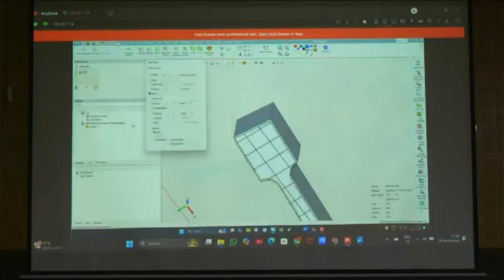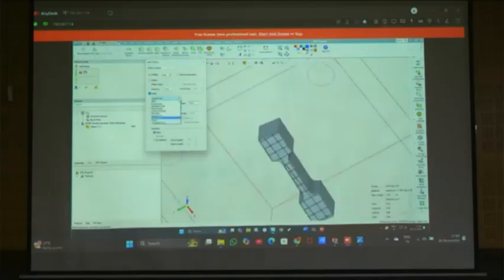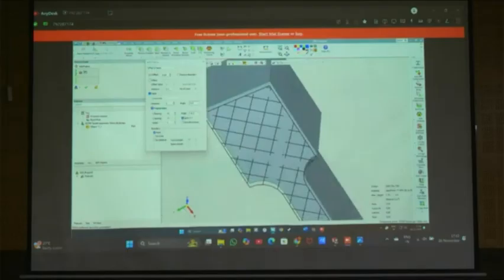Add pattern, so that it will add the pattern. Like this it will add the pattern, right? And square grid or something we can take. And distance I will keep 2, so that we can get more. Square shell. Usually I prefer cross line or square grid. Okay, this one. Fragmentation means if you apply the fragmentation, there are some gaps, see, so that we can easily break it. The support, we can reduce the post processing time. This is one of the techniques, fragmentation. So we can apply this pattern.